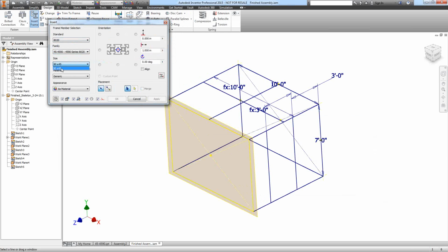If I had not selected as key columns my height and width, then I would have something here that would just say unnamed 1, for example. If you notice my 45-45, the size is just 45 because that's why I picked just a single parameter for that. So if you're publishing your own members, always add at least one additional parameter from your iPart table to your key columns when you publish. Otherwise, it's going to be hard for you to know exactly what you're getting here.